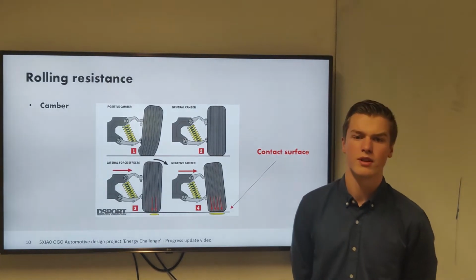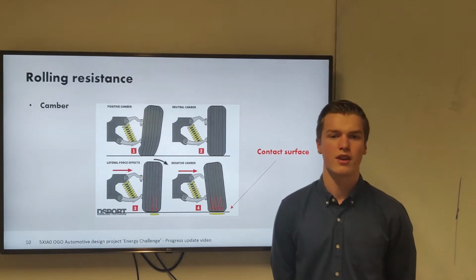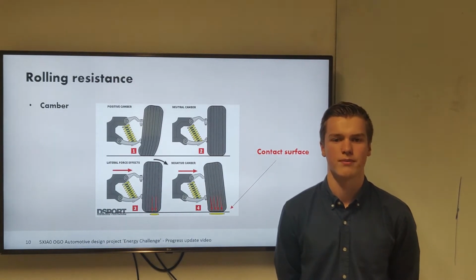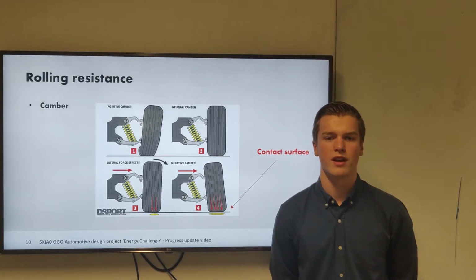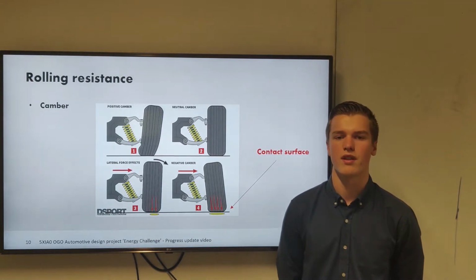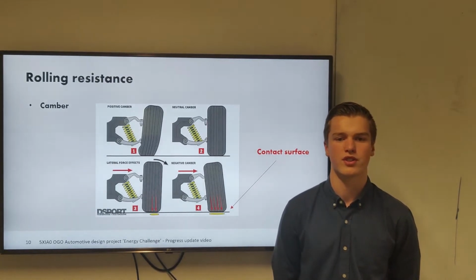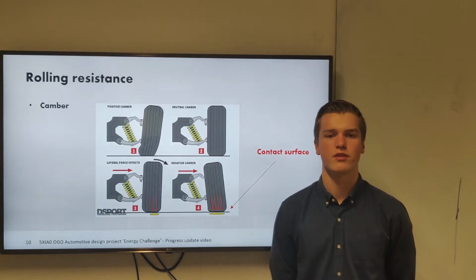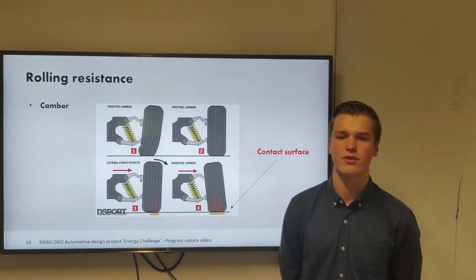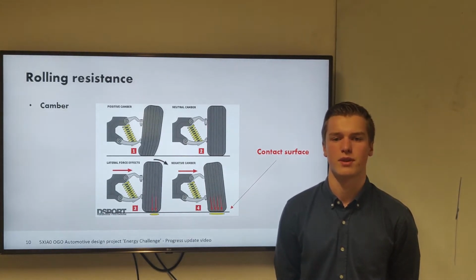Furthermore, we want to determine the contribution of the electromotor friction on the total of opposing forces. That is why we have to execute this experiment with and without the electromotor friction taken into account. By executing this experiment, we can determine the rolling resistance force and the rolling resistance coefficient as well.